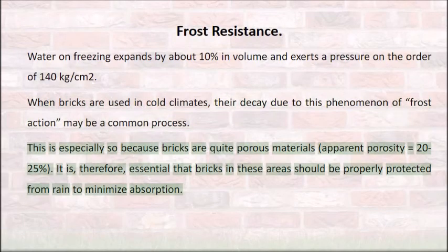This is especially so because bricks are quite porous materials. Apparent porosity is 20–25%. It is, therefore, essential that bricks in these areas should be properly protected from rain to minimize absorption.